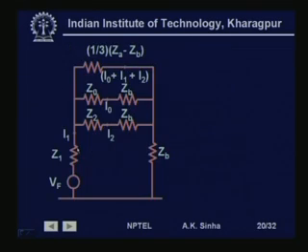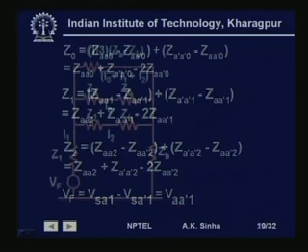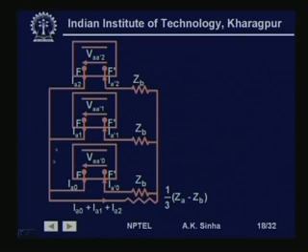These can be substituted here. So, we have the complete circuit now like this, V f with Z1 in series with that, and we have this current I1 flowing through this, and then we have this Z B here, and these are the 2 points of the circuit. And then again if we take zero sequence or negative sequence, then we have Z0 and Z B in series.